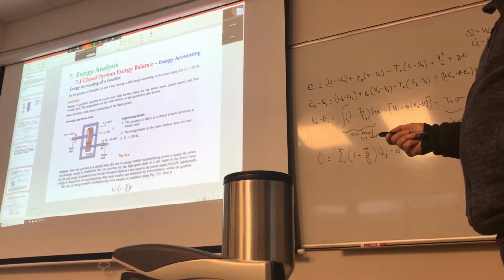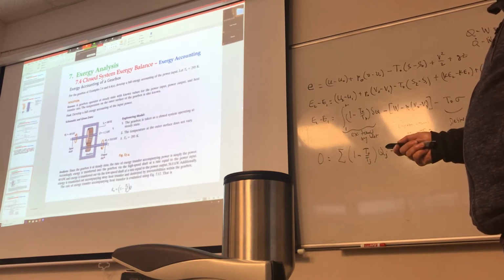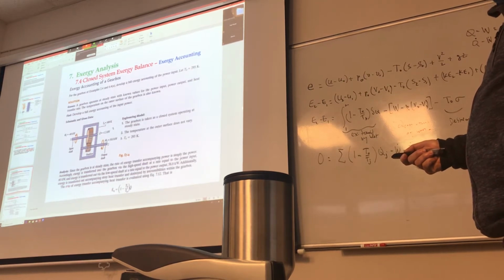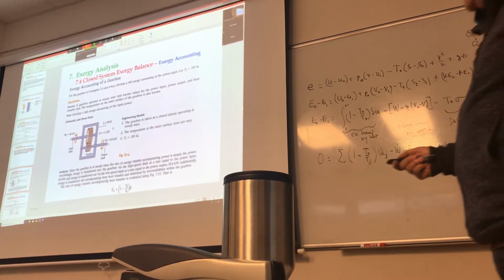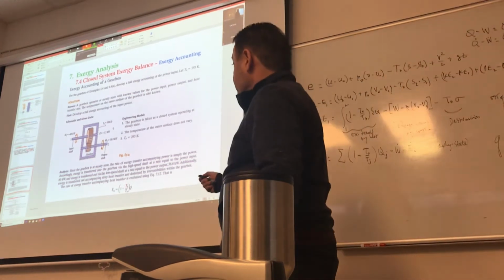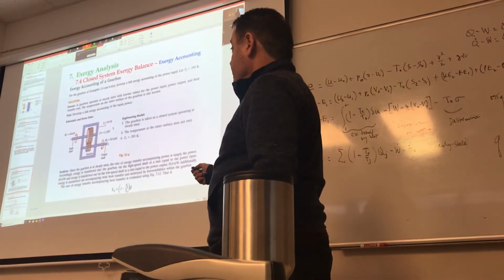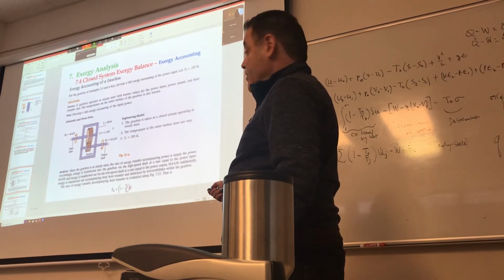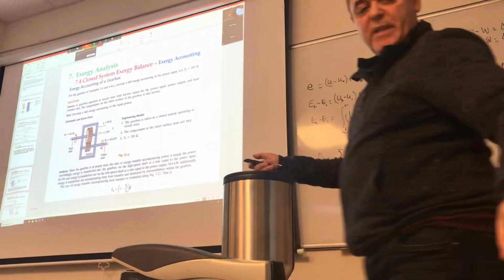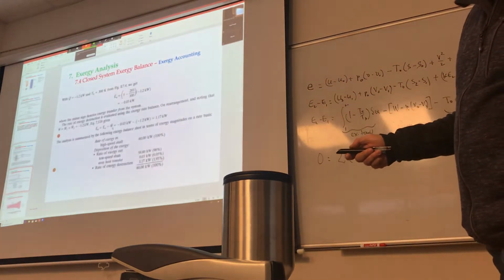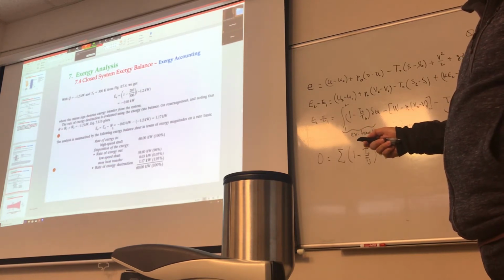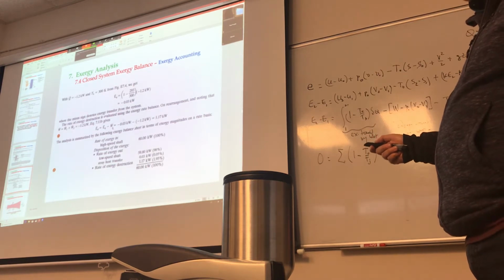So we got this, we got that. Now I lost my train of thought. Okay, Eq is 1 minus T naught over Tb, times Q dot. What is the temperature of the boundary? It's 300. T naught is given as 293. And Q dot is already known, so Eq can be calculated immediately, which happens to be minus 0.03. The minus sign denotes exergy transfer from the system.